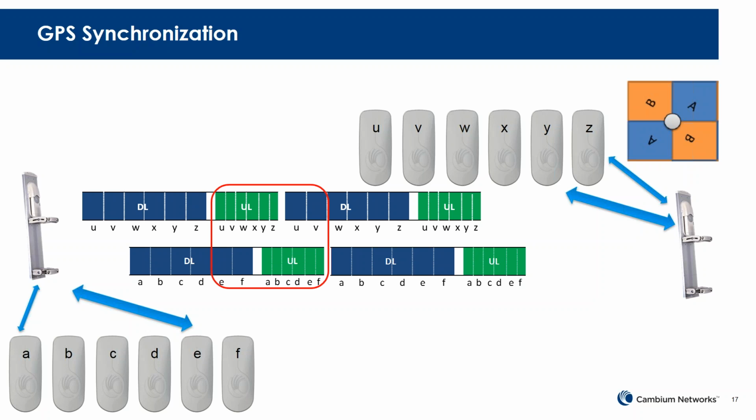And keep in mind that these remote radios may be installed 10 miles away or even more. So whenever one access point is trying to listen to this radio that's 10 miles away, and there's an access point that's a foot away that's talking, that other access point that's only a foot away is going to overpower and cause interference, so that the radio that's trying to listen to the other radio 10 miles away can't hear that weak signal.